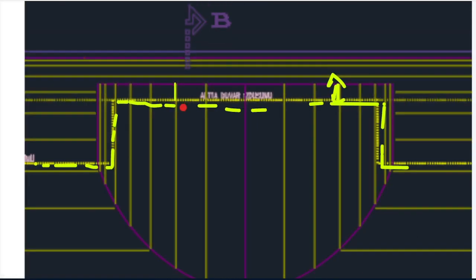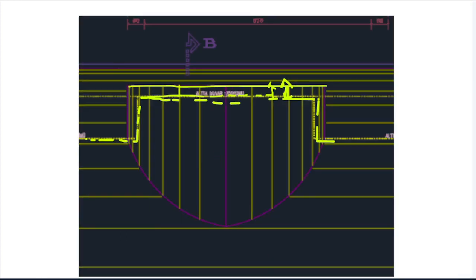What is the reason? The reason is that because of the rain, since you have a wall here at the bottom, this should be extruded at least 10 centimeters in case of rain, so you will have a safe place. Have you got it? This is very important again.